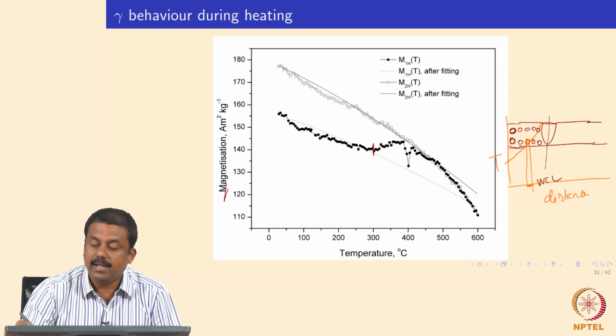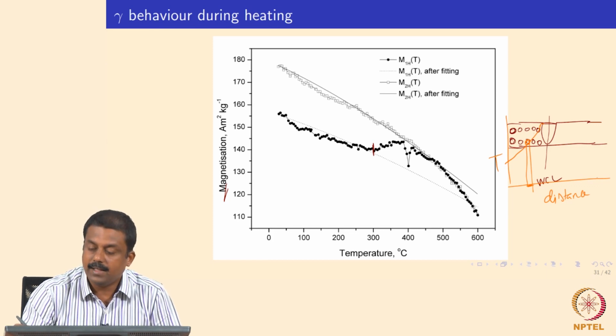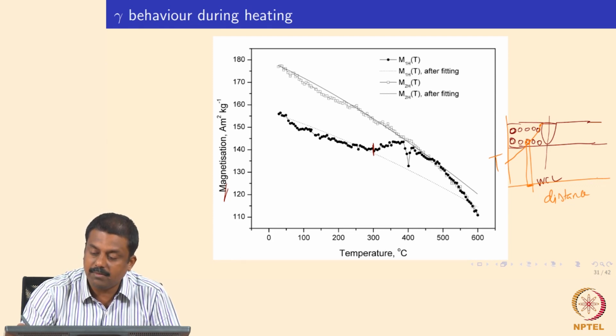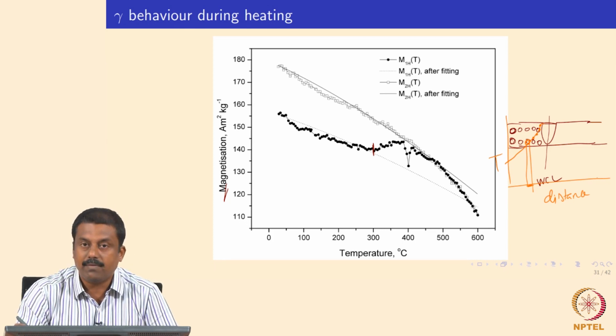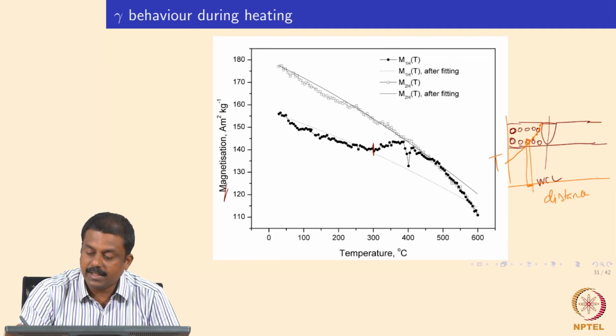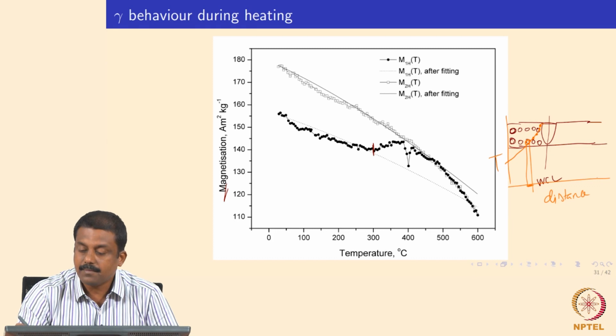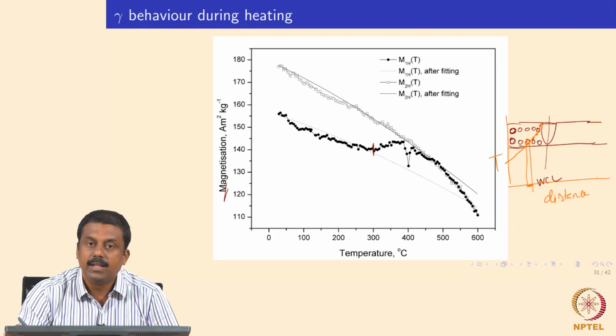If you want the effect of peak temperature on the retained austenite fraction, we need to measure with much finer resolution, isn't it? When you measure at a given location, the temperature should not vary by more than, say, 5 Kelvin. If that is the case, then we will have to make the measurements on a very small area of the sample.